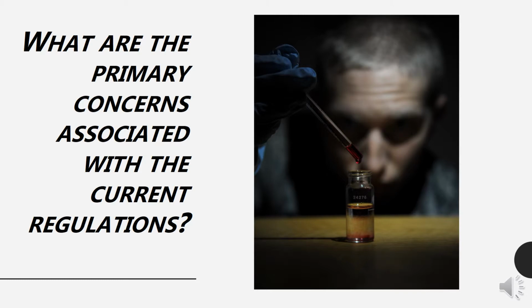Trihalomethane and haloacetic acid levels are regulated based on the sum total of species on a milligram per liter basis in a given water sample. What this means is that the weights of individual species are added up to quantify the total trihalomethane and haloacetic acid 5 levels. Since the molecular weights of disinfection byproducts increase with the incorporation of bromide, species containing only chloride have a lower weighting factor. This is a problem because some of the chlorinated regulated species, such as chloroform, are considered less dangerous than brominated compounds like bromoform, which can lead to the misrepresentation of public health risks of a given water sample.